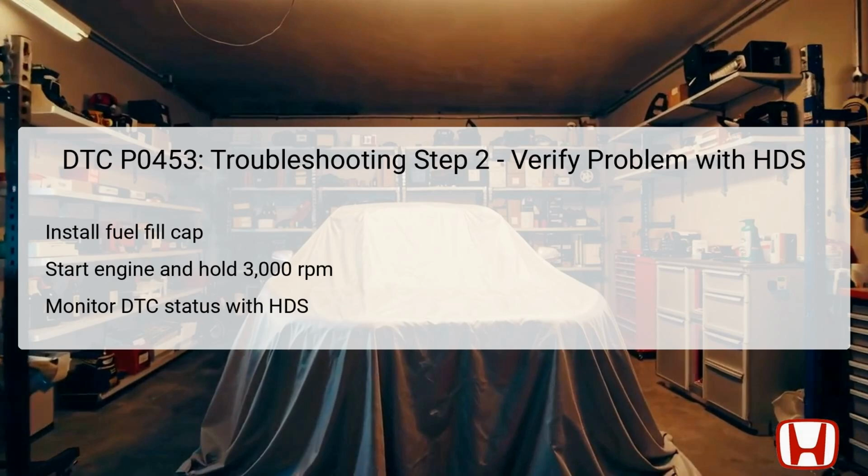The second troubleshooting step focuses on verifying the persistent nature of the DTC by testing the system under operating conditions. After installing the fuel fill cap securely, you start the engine and set it to 3,000 RPM without load, meaning the vehicle should be in either park or neutral. This steady-state operation helps simulate conditions under which the high-voltage abnormality might manifest.